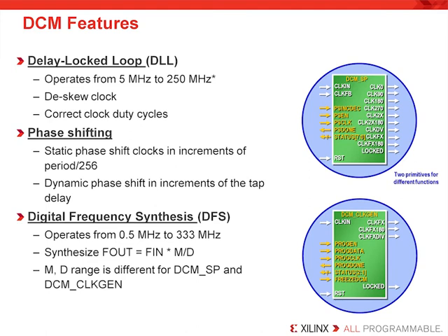If you've used the DCM before, you should note that it is no longer necessary to specify a low or a high frequency mode for the DCM. In the case where a customer is, of course, using the architecture wizard to customize their DCM component, then the DCM will automatically be customized based on the frequency the user specifies with the architecture wizard. So, in effect, very little thinking has to occur by the user in the customization.